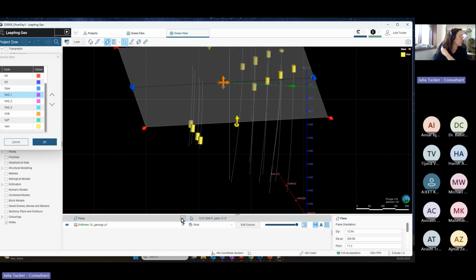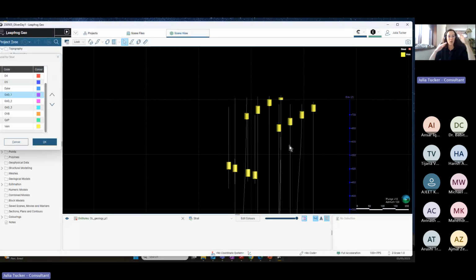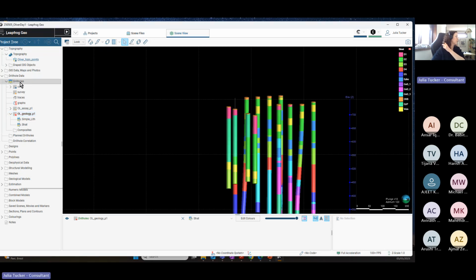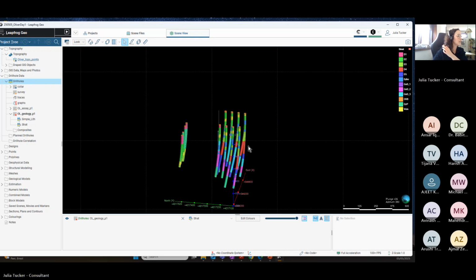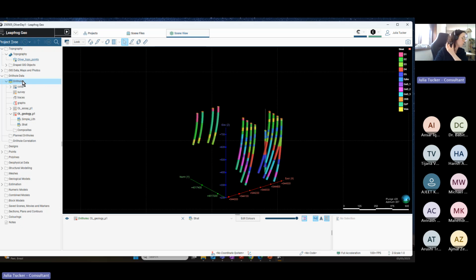So this is important for us to understand how this is behaving and how we are going to make this behave as we want. And now we just need to start doing what we need to do, that is to group the granodiorites and to split the dike into two. So we are going to split the dike by interval selection, that is right here on the drill holes, and we are also going to group the lithology right here on the drill holes too.